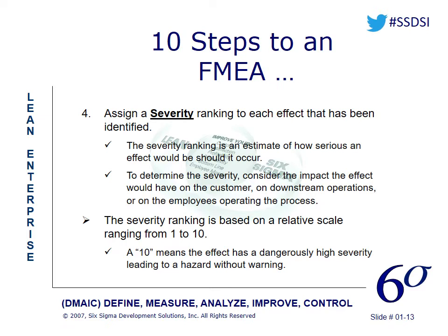Next, we fill in a severity ranking. Actually, I'm going to back off of that. This is kind of put in the wrong format, because the 3 scores that I'm going to give you, severity, occurrence, and detection, help us understand the true risk of the effect. These 3 scores actually do not get filled in until the end of your FMEA.